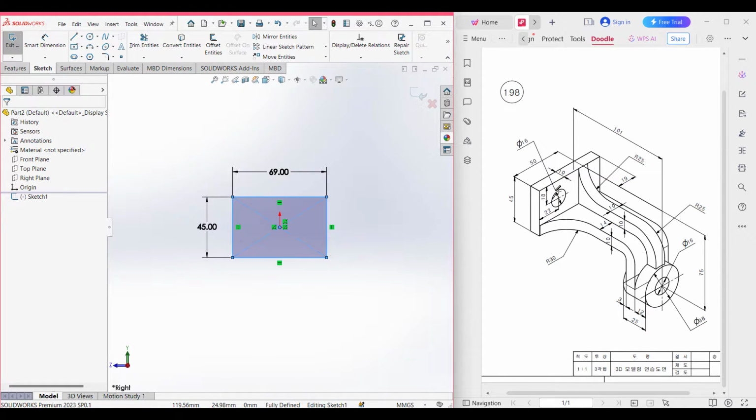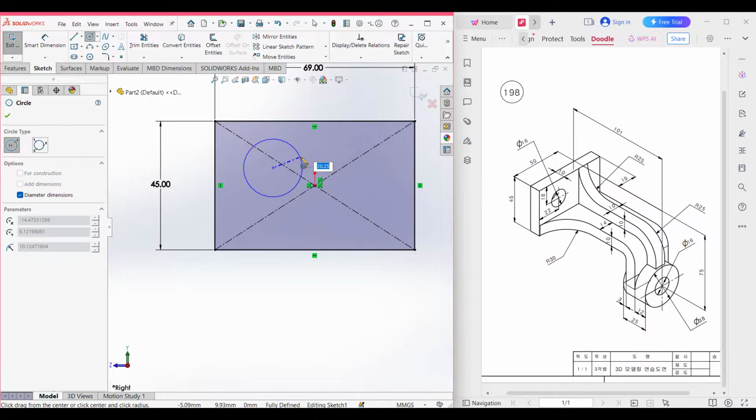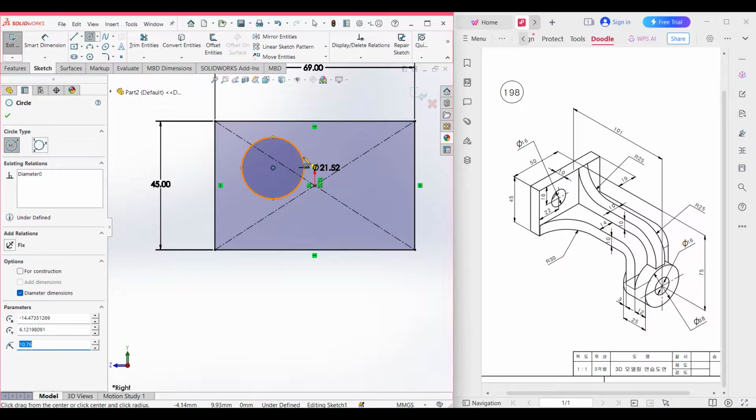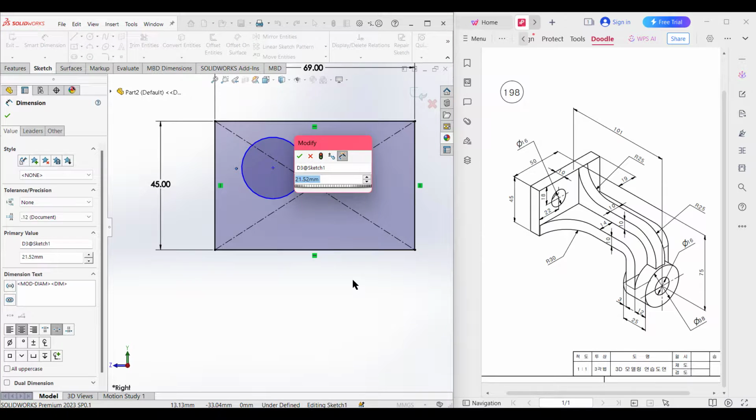Let's go back to our sketch. In our sketch, we have an extrude cut circle here, and this extrude cut circle has a dimension of 16 diameter, and it has a distance of 18 unit from here, and another distance is 22 unit from another side. Okay, so I'm doing it here. Now select the circle tool from here and draw a circle of 16 diameter.